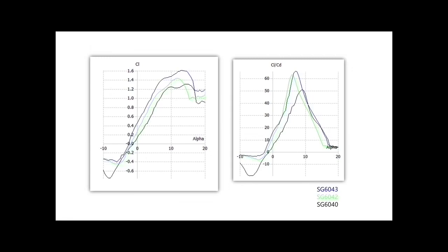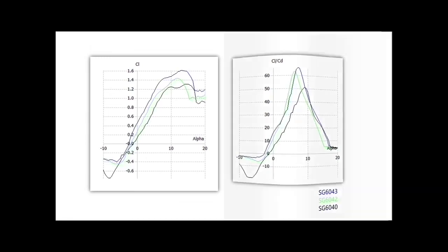A two-bladed design has a disadvantage of gyroscopic precession, a phenomenon resulting in wobbling and unwanted twisting effects, placing extra stress on the turbine components. While SG6042 and SG6043 show comparable aerodynamic performance, research shows that SG6042 is regarded as being more structurally sound. Therefore, we chose this airfoil as it offered the best compromise between aerodynamic performance and structural integrity.